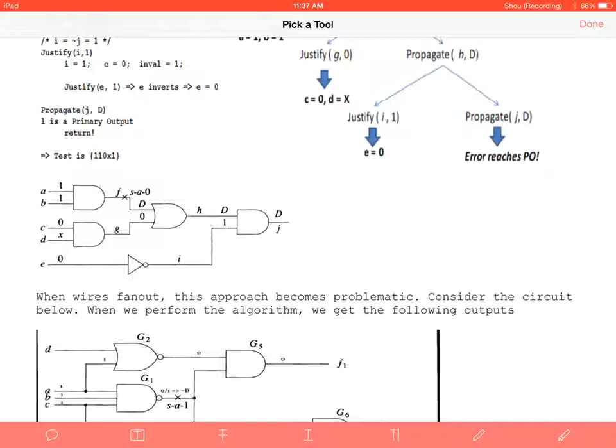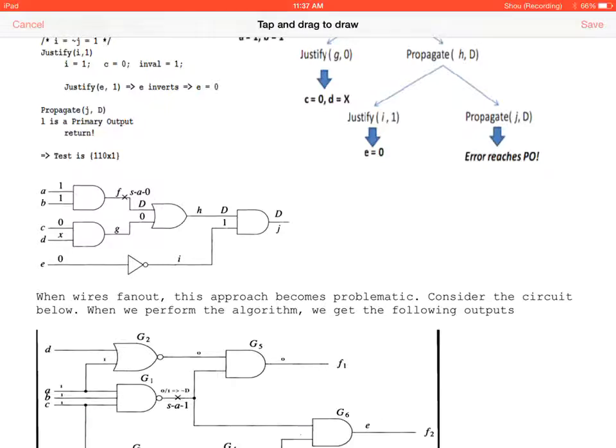Yes, Thomas. For the A and B input AND gate, whenever we put 1, 1, why are we getting 1, 0? Okay. Because of the composite logic function. The problem is stated as a stuck at 0 fault, right? Correct. This is a good question, so I want to make sure I emphasize this enough. What I mean by 1, 0 is that when it's 1, 1, the function should be 1, but it actually becomes 0.